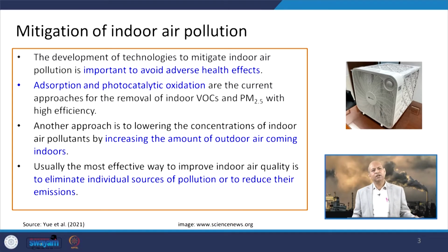Then there are several techniques, but adsorption and photocatalytic oxidation are the current approaches which are popularly used for removing indoor VOCs, volatile organic compounds, and fine particles like PM 2.5 with high efficiency. These two processes, adsorption and photocatalytic oxidation, are very popular in that sense.